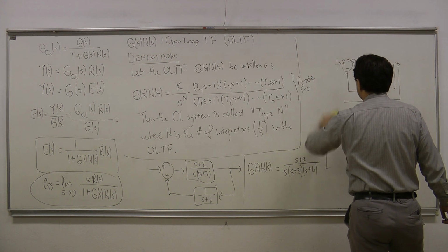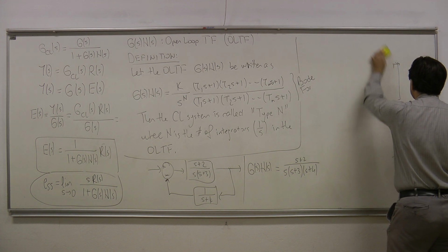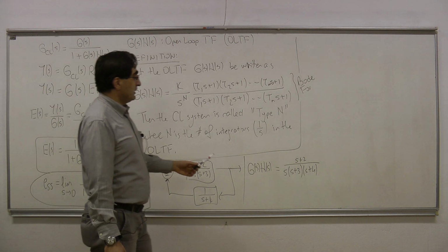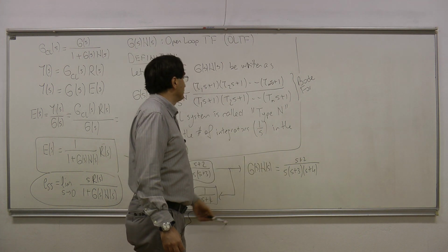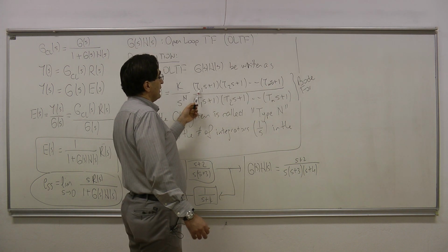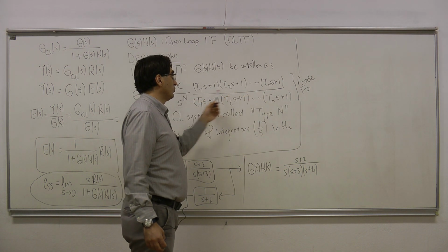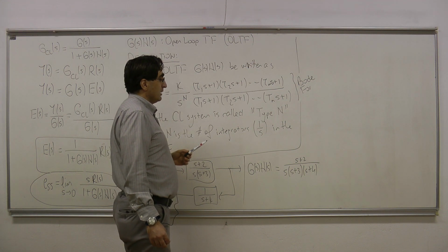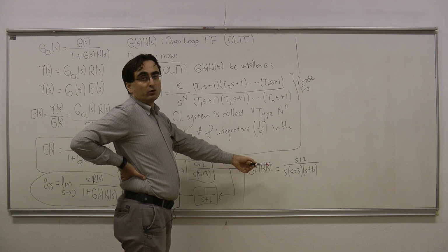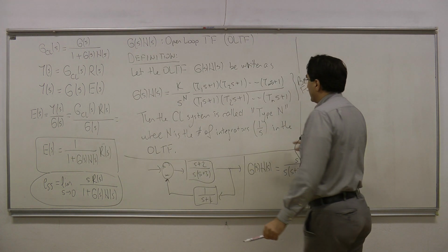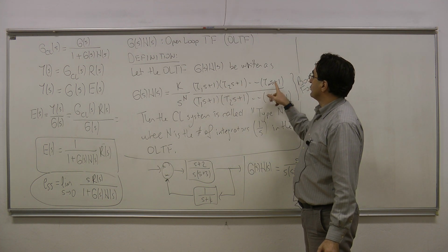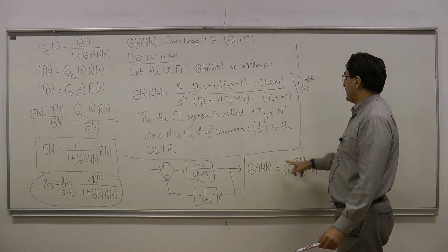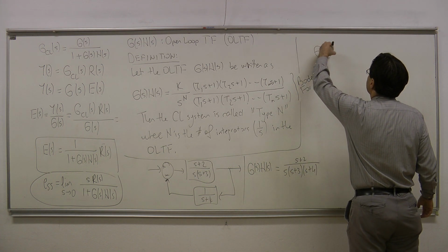So now, do you think this open loop transfer function is in Bode form? Your answer should be no here, okay? Because here the terms are like s plus 2. In the general form I have m zeros, and I have n poles like this, and I have capital N poles at 0 as well. So now let us try to put this transfer function in Bode form. Okay? How can I do that? I need to make the constant terms here equal to 1 in both the numerator and the denominator. Okay? So here I have a K parameter, G of s, H of s.